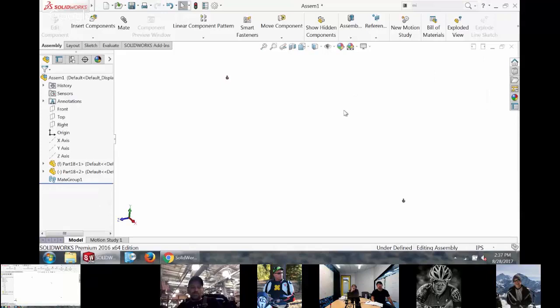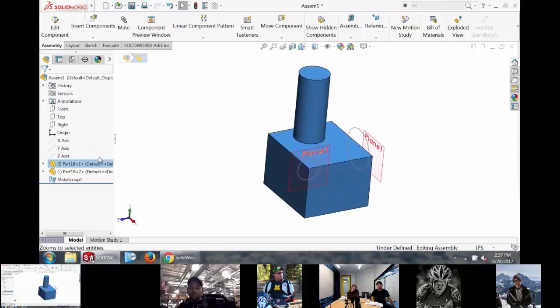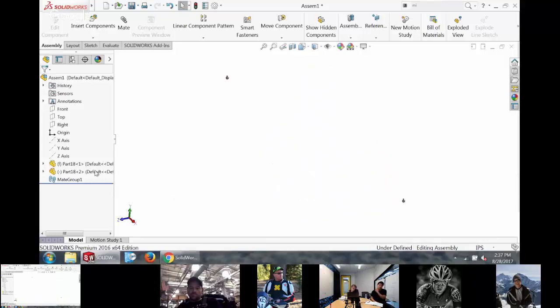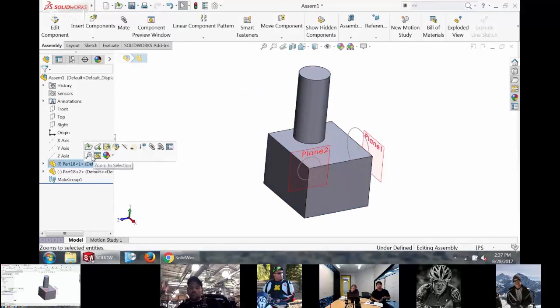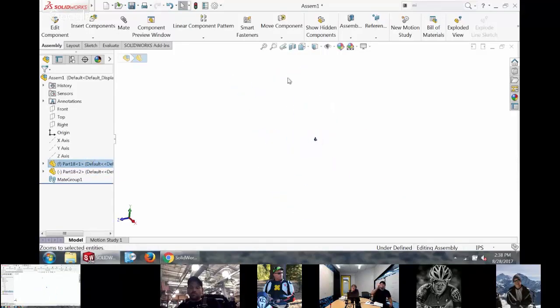When you've got something like that, typically what I'll do is I'll find a part that I really know where it should be and I'll zoom into it just to make sure that I don't have that hidden body thing. That, yes, I can see that. And then just start figuring out, when you click on something, do a fit screen, you can figure out where they are in relation to one another.